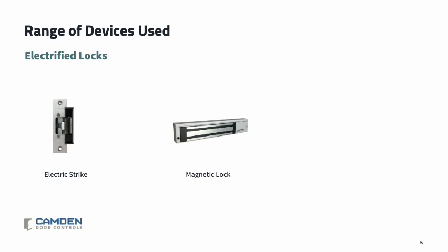Although not used as often, I have seen magnetic locks being employed for this application. If this option is selected, however, please be careful because an override switch or power disconnect switch may actually be required by your local authority. Lastly, a mortise or cylindrical electrified lock set can be used. This lock replaces the standard mechanical lock set, and although these may be easier to install than cutting an electric strike into the door frame, you will need a power transfer cable to run wires from the frame to the lock that's mounted in the door.